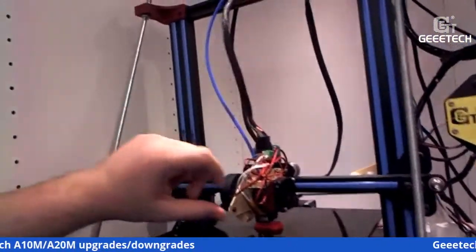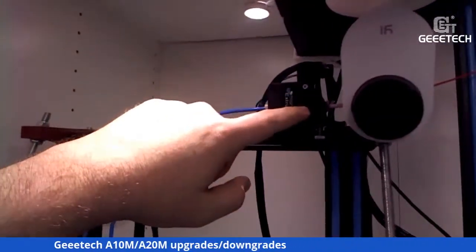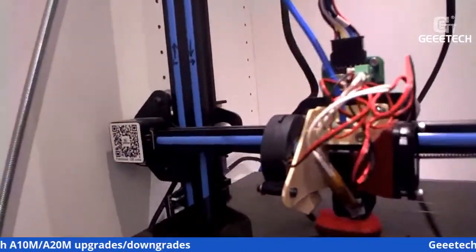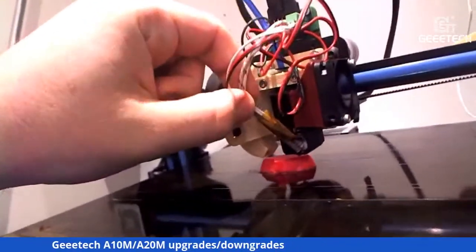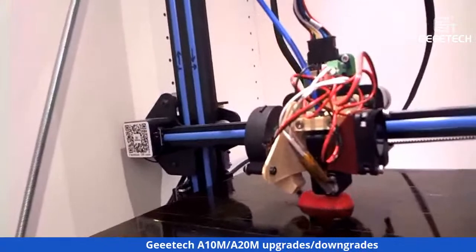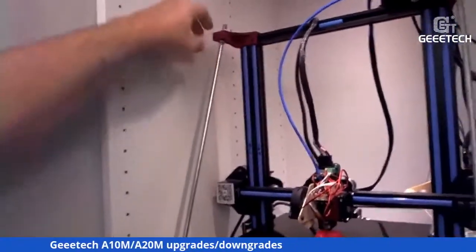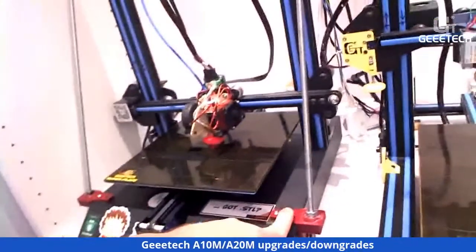What I did here, I upgraded it with this Geeetech extruder. This has a 3:1 ratio. That means it has 3 times the force of the extruder motor. And here we have also a custom made part, a Mosquito Hot End. So this one is a Mosquito Hot End with custom made support for the A20M here. And what was a problem with an A20M, and I think I solved it with these stiffeners. So you can see here are the stiffeners,